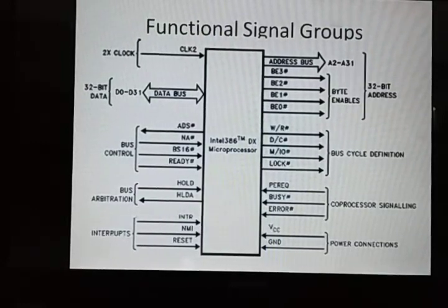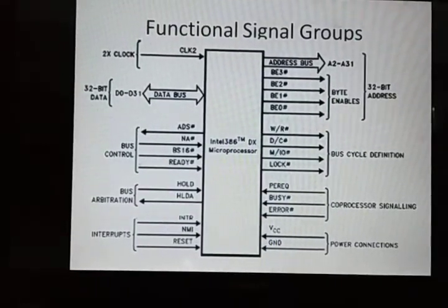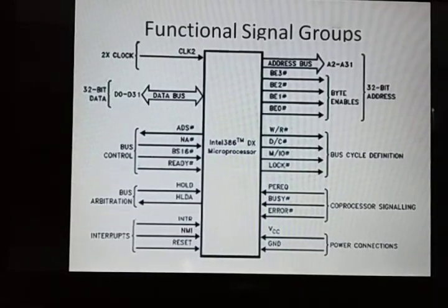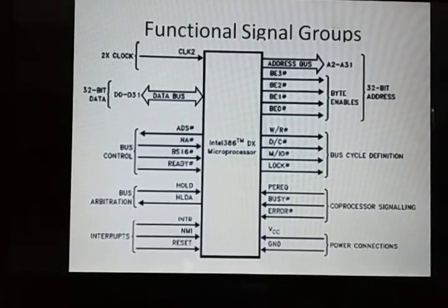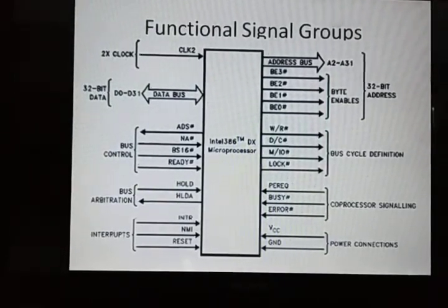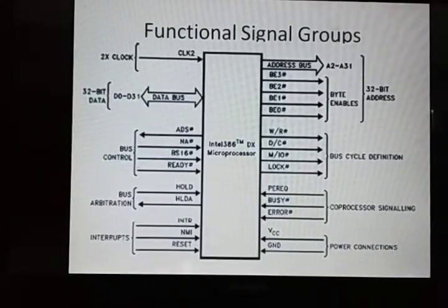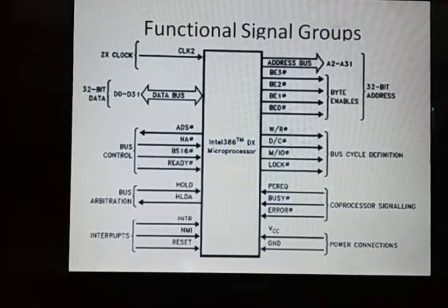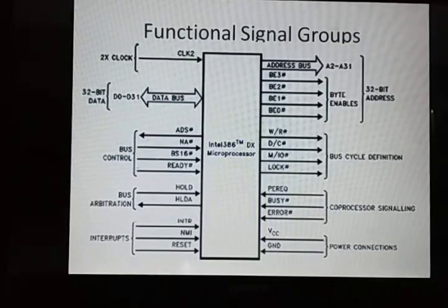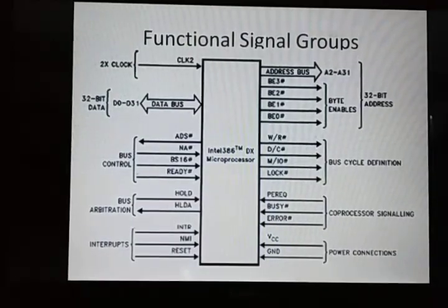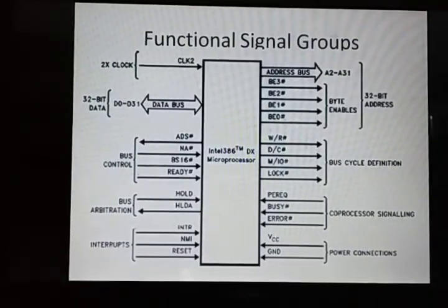These three pins behave like interrupt pins, and we have discussed in the previous lecture what an interrupt is. An interrupt is nothing but a signal to the processor, emitted by the hardware or software, indicating an event that needs immediate attention. Your processor is executing some task, and if an interrupt is generated during the execution, the processor identifies whether it is a non-maskable or maskable interrupt, and according to that the processor executes the interrupt process.